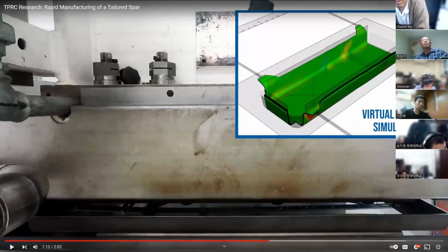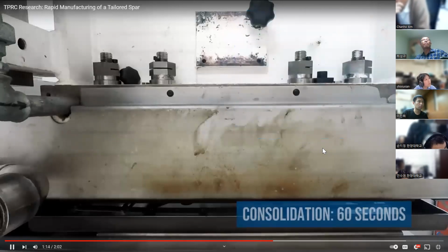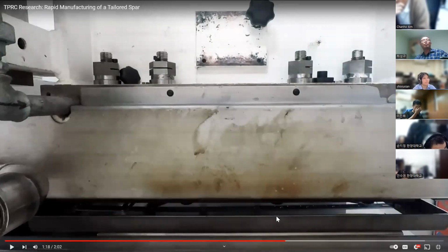So virtual forming simulation means that, starting from the layers, we simulate how they can deform, similar to undulations, and then consolidate. In the composite curing process, for thermoset we call it the curing procedure, and for thermoplastic we call it consolidate. There are two different words: one is consolidate, the other is curing. Curing is usually for the thermoset, and consolidate is usually for thermoplastics.